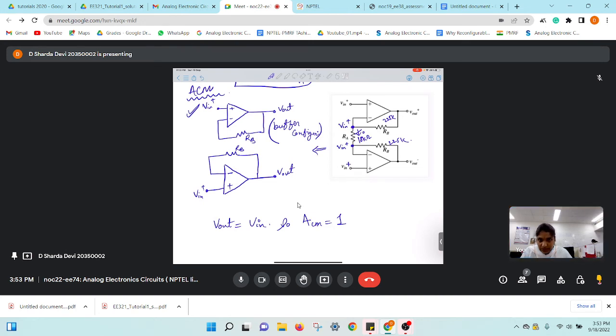I have a question, ma'am. Yes. This buffer has a resistor, right? Does it play any role? No, it won't be playing any role. Because there won't be any current inside, right? So I will be simply equal to 0. So the moment I is 0, this makes these two equipotential. So it will be a simple buffer. So this R is also not playing any part. Sure, ma'am. Understood. So is this clear to everyone? How we got our ACM to be 1? Is this clear? Yes, ma'am.